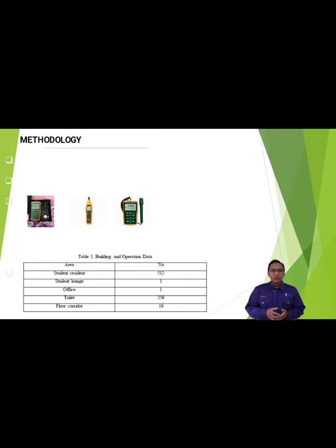Post-audit were followed to determine the energy consumption index, including building energy index, air conditioning index, and lighting energy index. This index represents the actual energy consumption of the building by on-site measurement. Finally, energy and cost saving were calculated to recommend preventive action of excessive energy consumption, or ACM. The audit areas of KK4 building and operation data are summarized in the table below.